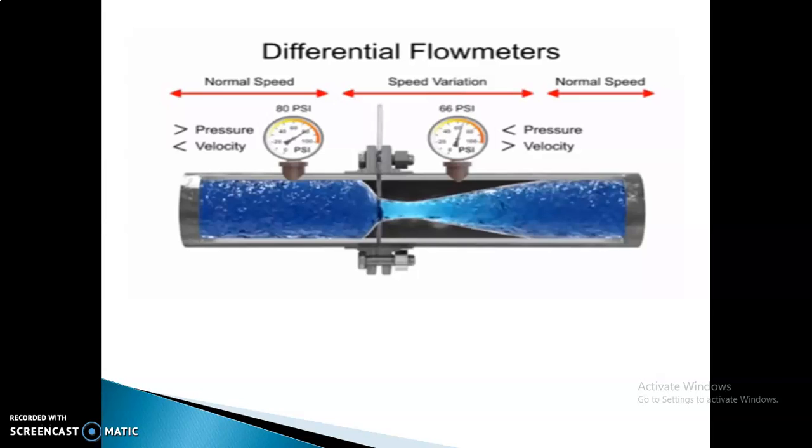The pressure drop is measured using the differential pressure sensor, which is nothing but a U-tube manometer, kept on the tubes of this portion. This is how we can measure the pressure difference. A1 is the cross-sectional area of the pipe, A2 is the cross-sectional area of the orifice, and P1 and P2 are the static pressures. This is how the measurement is done in orifice plates.